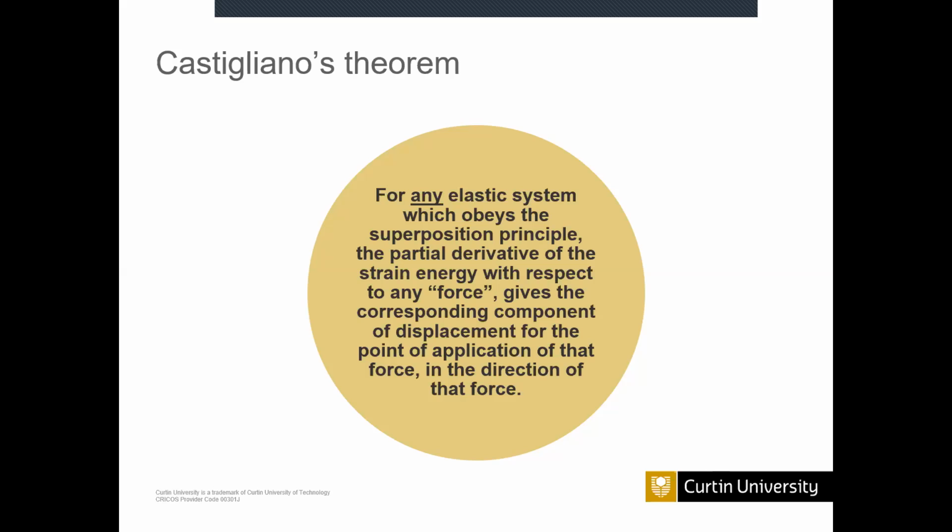If you have the load at that point towards the upward, but the deflection is downward, you can't use that particular load towards the upward. So you need to introduce a dummy load towards the downward. Hope you understand that. So this is the Castigliano theorem for an elastic system which obeys the superposition principle. You don't need to keep this word by word in mind, just get the idea.